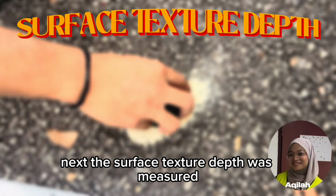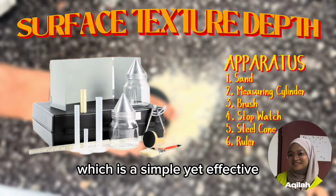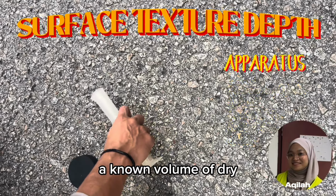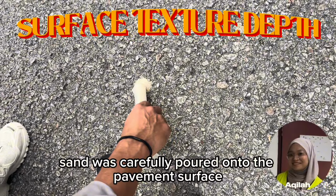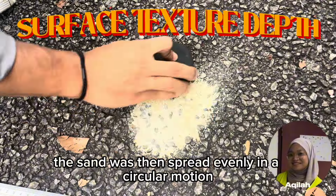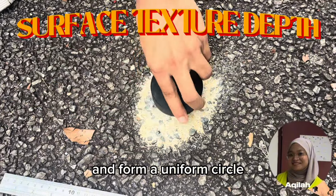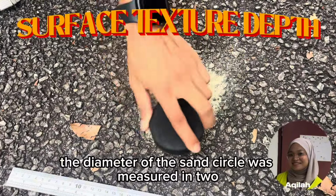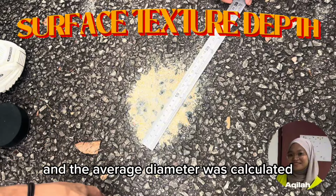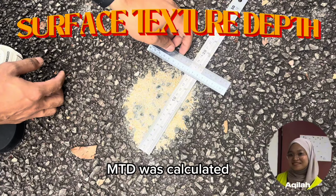Next, the surface texture depth was measured using the sand patch method, which is a simple yet effective technique for determining the microtexture of pavement surface. A known volume of dry sand was carefully poured onto the pavement surface. The sand was then spread evenly in a circular motion using a flat disc until it filled the surface voids and formed a uniform circle. The diameter of the sand circle was measured in two perpendicular directions, and the average diameter was calculated. Using this measurement, the mean texture depth (MTD) was calculated.